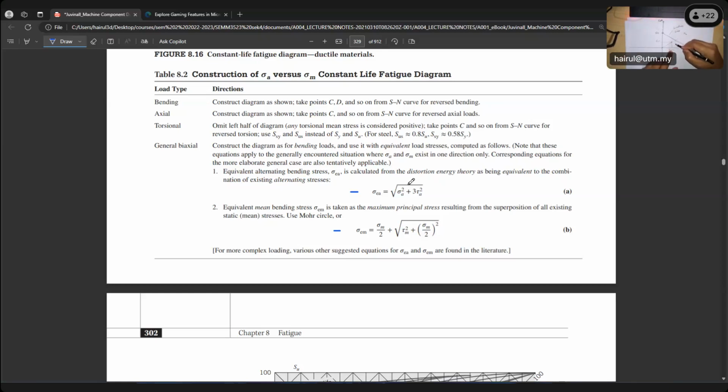So this will be your Sm, because this is sigma mean. So strength mean in your case, because your loading point is here. So you extend it up until it intersects; this is the border of failure. So this distance is Sm. You bring the border down. So your sigma em. So safety factor can be Sm over sigma em. You can calculate by using the graph.